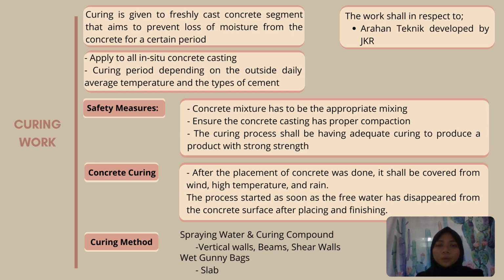So some of the safety measures that we apply during the project is the concrete mixture has to be appropriately mixed, ensure the concrete casting has proper compaction. The curing process shall have adequate curing to produce a product with strong strength.